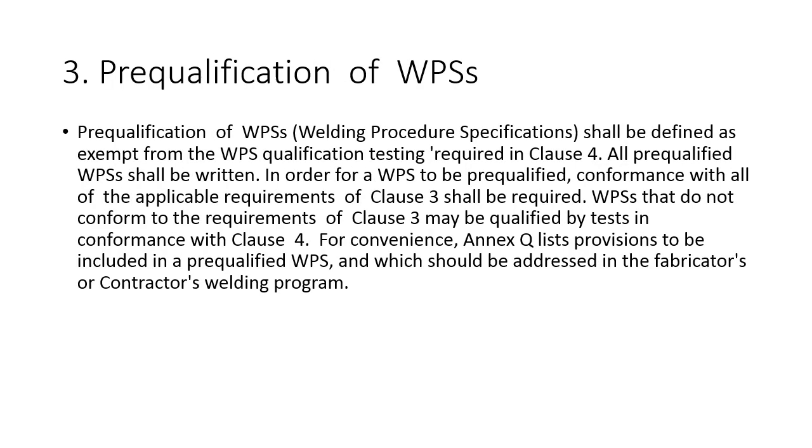Pre-qualification of WPSs. Pre-qualification of WPSs, welding procedure specifications, shall be defined as exempt from the WPS qualification testing required in Clause 4. All pre-qualified WPSs shall be written. In order for a WPS to be pre-qualified, conformance with all of the applicable requirements of Clause 3 shall be required.